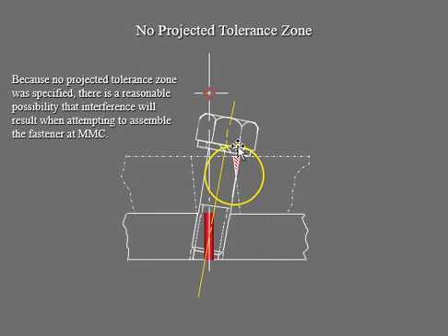So when you look at it and we put that in, see that the bolt is completely going in an inclined direction like that. So that's a huge error. If you think about an aeroplane having this type of mating, it is going to bring the entire plane down. Why? Because the environmental forces can threaten this misaligned joining. So they carefully check every fastener and fit. And if they find something like this, then you're going to restart everything again, okay? So it's really important.